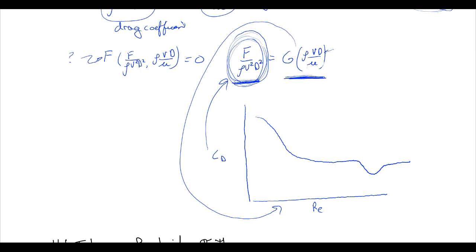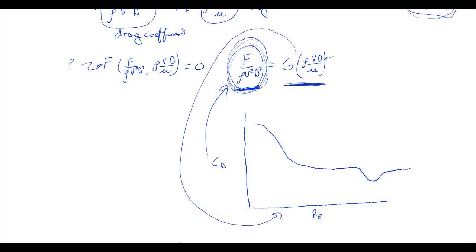This drag coefficient Reynolds number relationship works for, I won't say all, because if you get towards compressibility effects, then this doesn't work. But then you're missing out on some stuff, but we'll talk about that in a little bit. So it doesn't work for everything, but as long as you're within a certain range of Reynolds numbers, you'll be able to calculate your drag coefficient for your object.